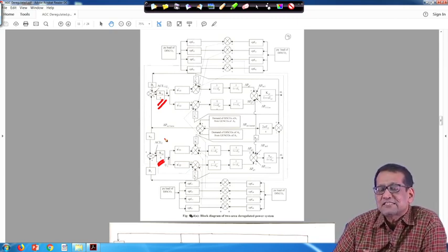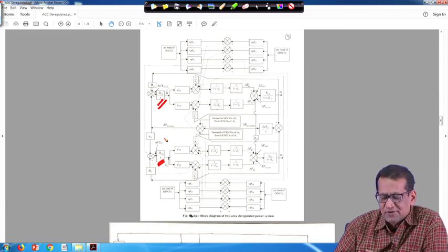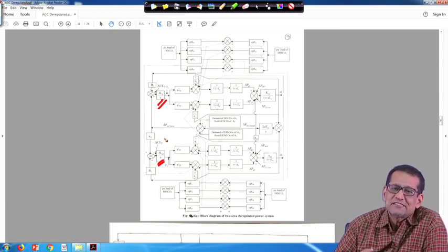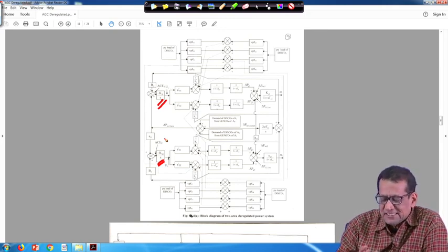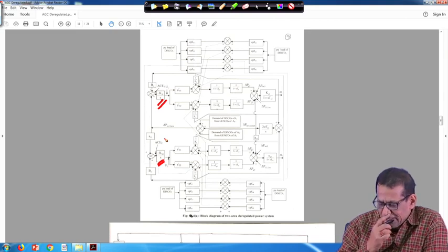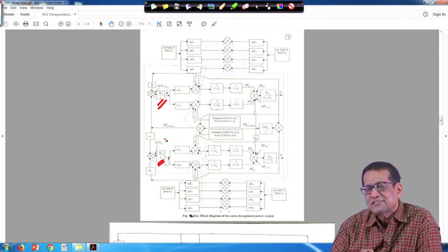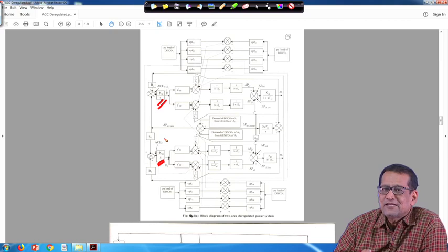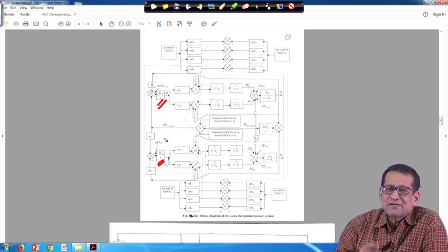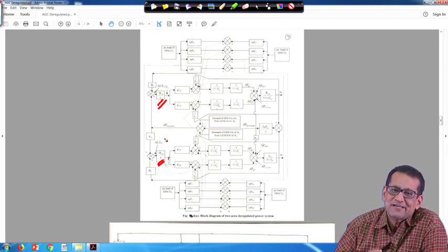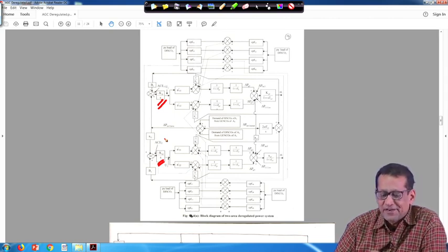Otherwise the system will become unstable. Very small integral gain, and proportional may also be very small, but integral gain is preferable. If you want to experiment with PID, I told you for a hydro system derivative is okay, but for a thermal system derivative action is not recommended. You find out why that is.